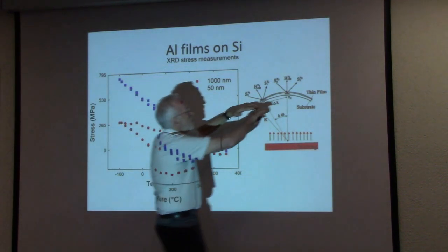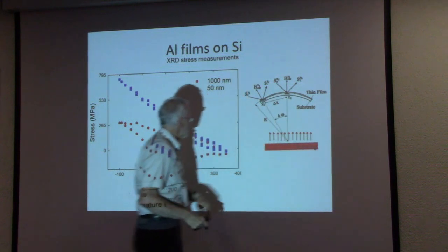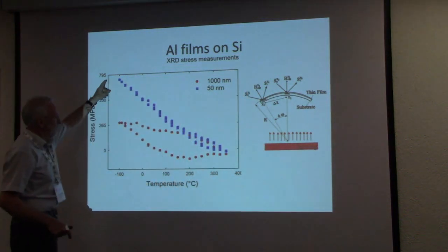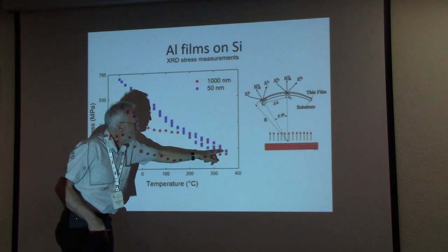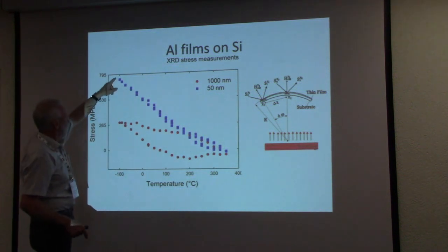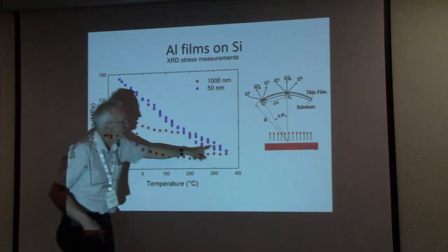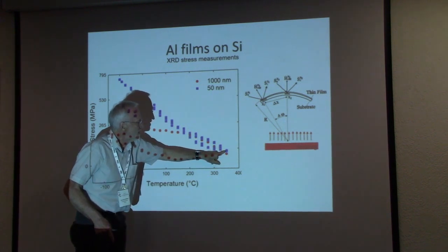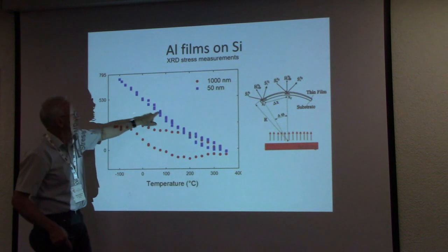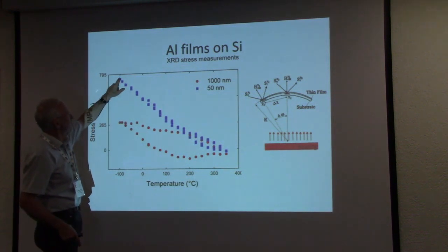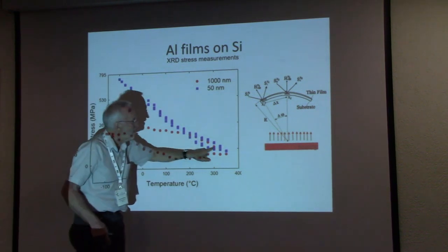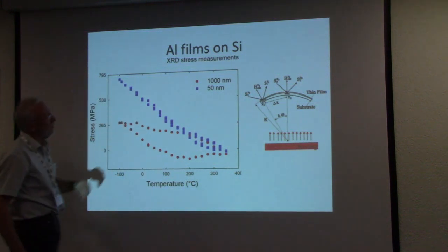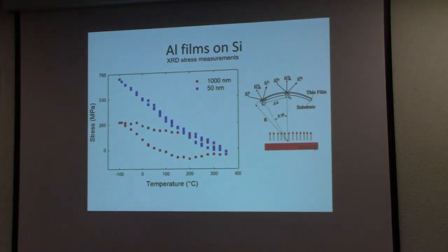Simply from the bowing you can determine the stress. You get the pure elastic loading of the film. Then you go in compression at very high stress, which then determines the stress in tension. But it always remains nearly linear elastic. Very little plasticity takes place.